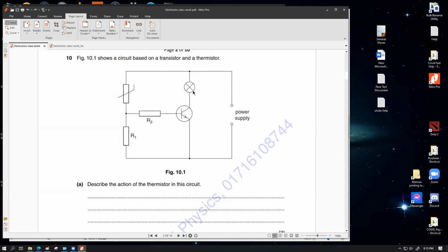If you think about, let's say, what if we don't use a filament bulb? If you use another type of bulb as well, every device has a rated voltage and power. For example, let's say a normal fluorescent lamp. It has a rated voltage of 220 volts, 60 watts, which means whenever you provide 220 volt AC across it, it is going to consume a power of 60 watt from the supply line. The light will be something less because it will always have some heat associated.